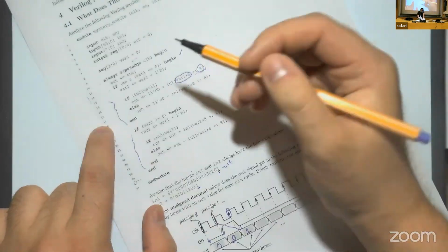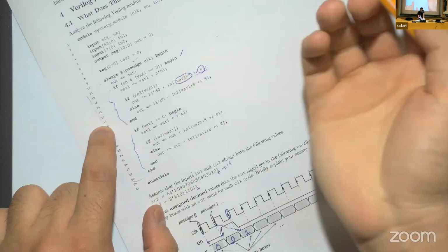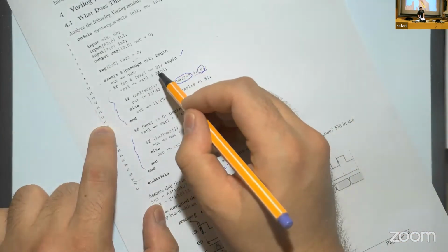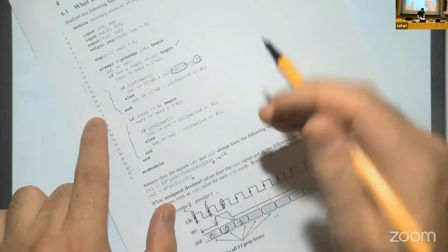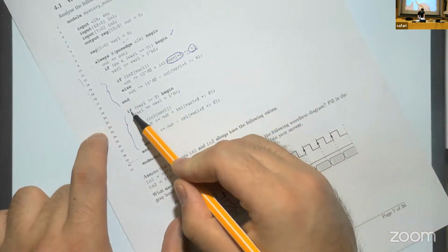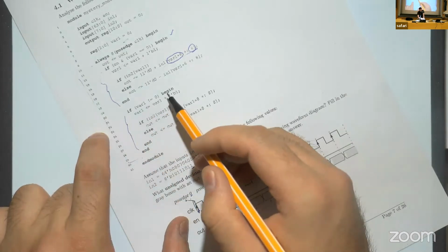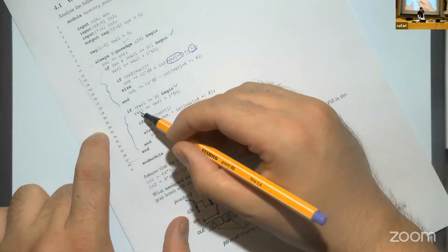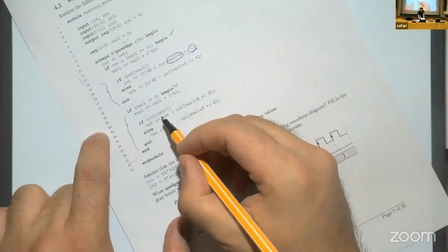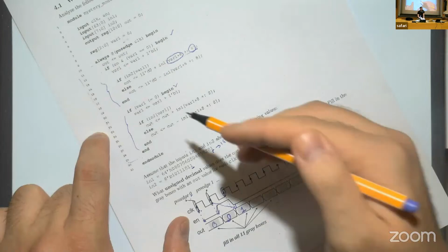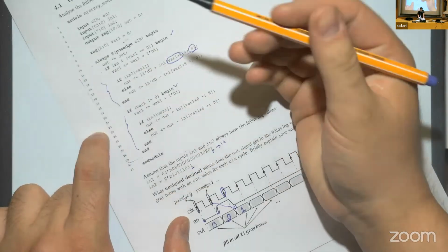So let's execute that one again. Enable is now, it doesn't matter, variable 1 is 1, so we don't go into that block. And we check this if, the 21st line. Variable 1 is not 1, so now we go into that one. Variable 1 becomes 2 here, but it will be updated after this always block has executed.